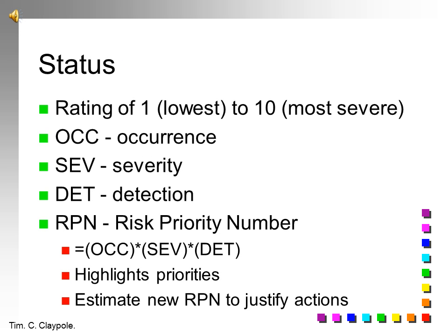This slide specifies how we calculated the risk priority number, much as I described when we were looking at the last layer. You have occurrence, the severity, the detection, the risk that we've got it wrong and we've not noticed that we've made a mistake, and that multiplied together, these give us the risk priority number.